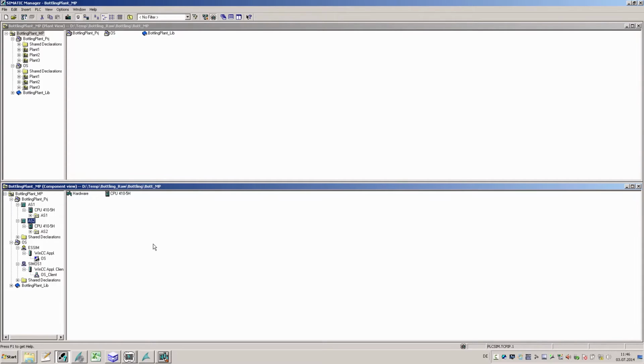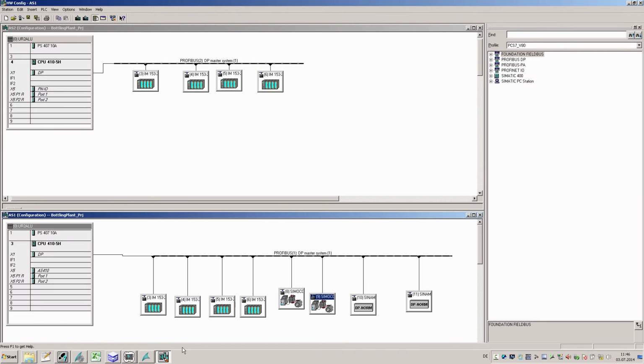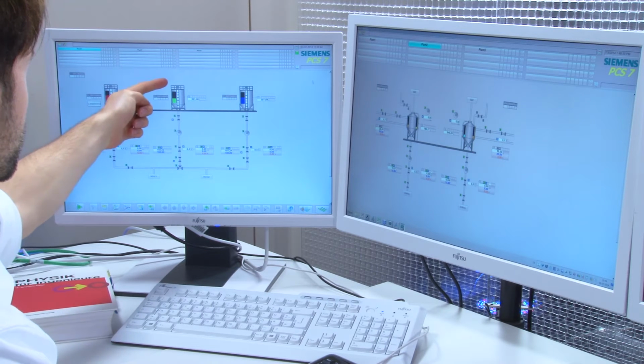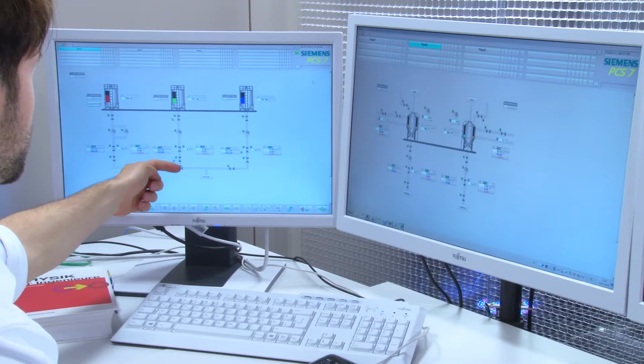In this video, I will show you how you can commission SIMATIC PCS7 automation projects virtually using SIMIT simulation framework. First of all, I need an overview of the way in which the plant behaves. I have to understand which devices, in other words, actuators and sensors, I have in my project and how they behave in physical terms. In the example, liquids are pumped from 3 raw material tanks into 2 reactors.